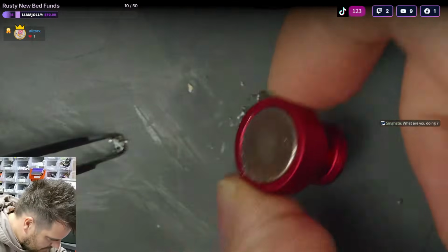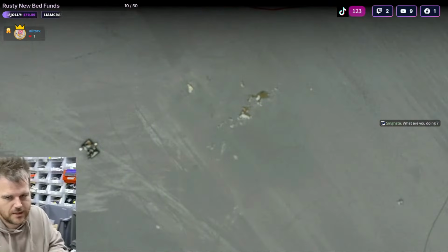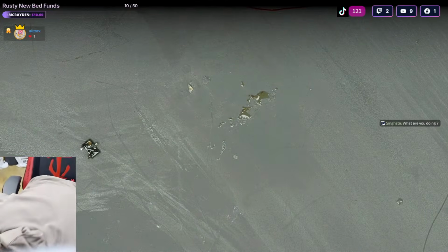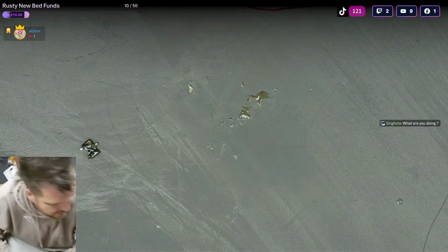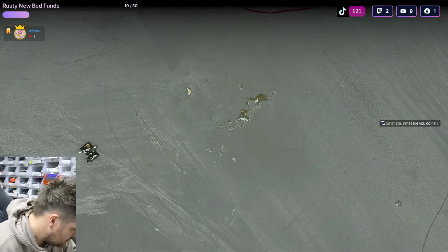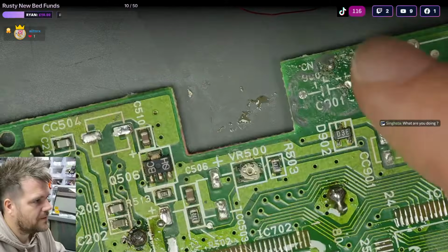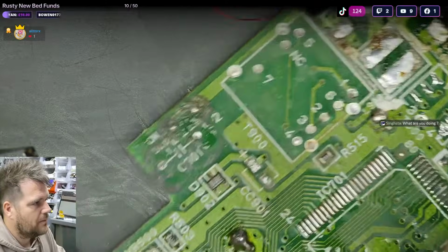Normally when I'm working on tiny chips like this, I just use blue tack. I just need to see if I can find some, because this is just going to disappear when we come to solder to that. Or what we could do, tell you what, another trick. We can get this board. It doesn't matter what pin we go to.